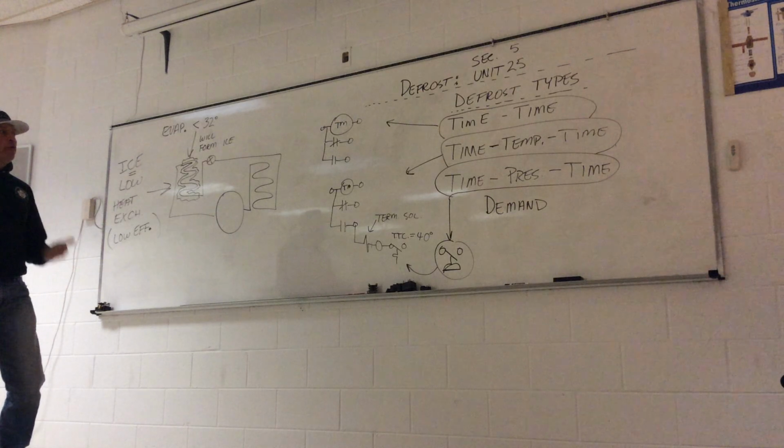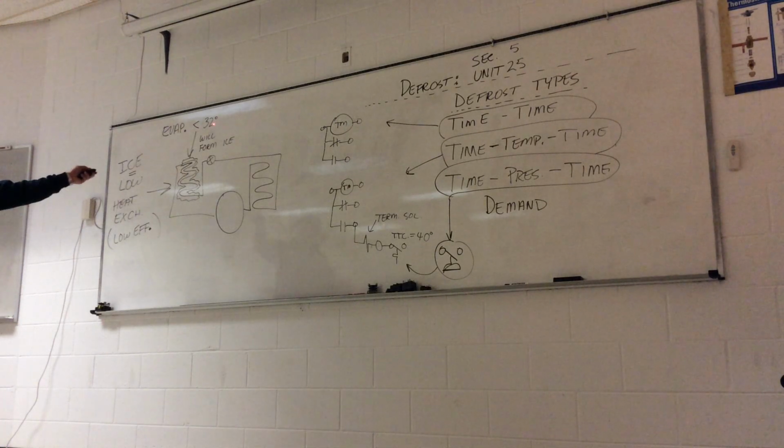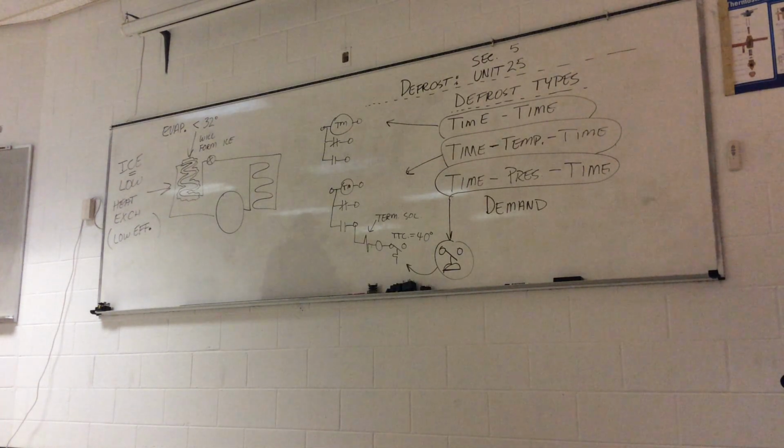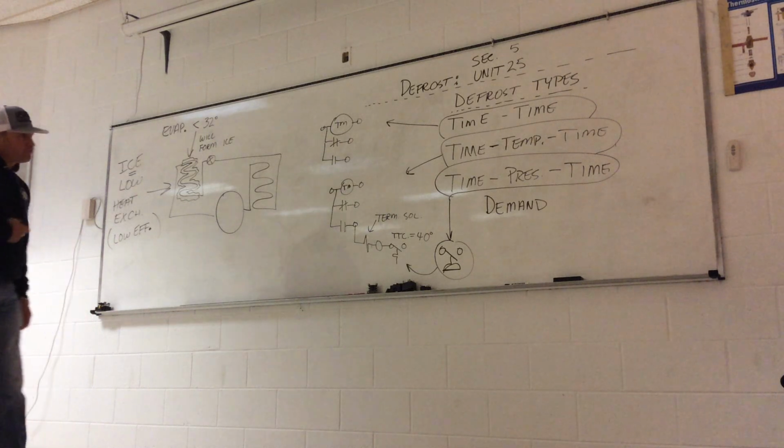So we have to go through periods of time where we go into defrost. Okay? And when is that? Anytime we have evaporators less than 32 degrees. The colder the evaporator goes, usually the more we're going to have to defrost.